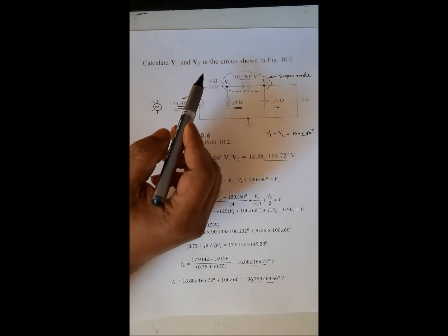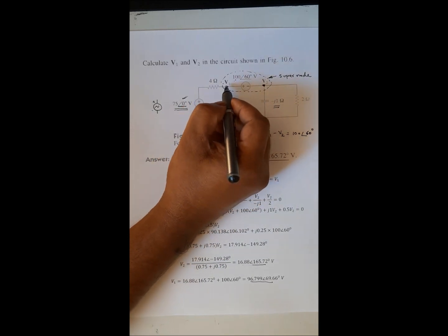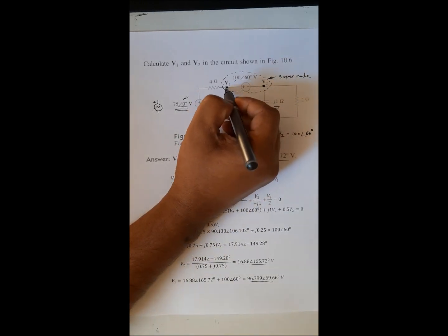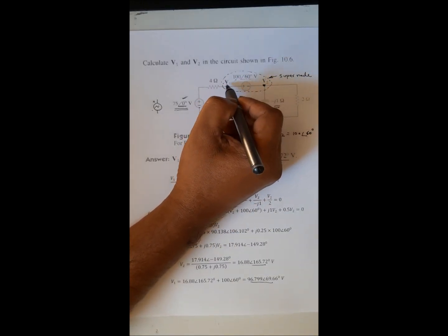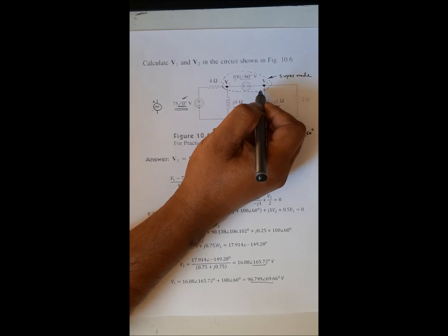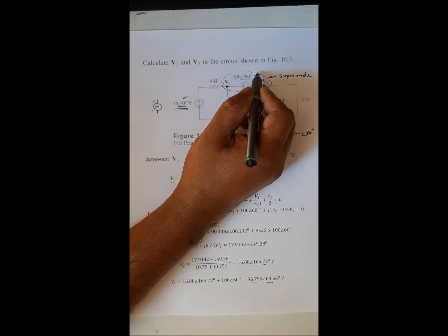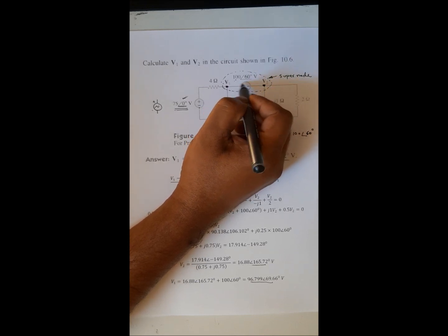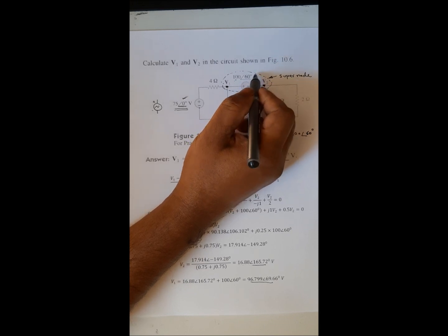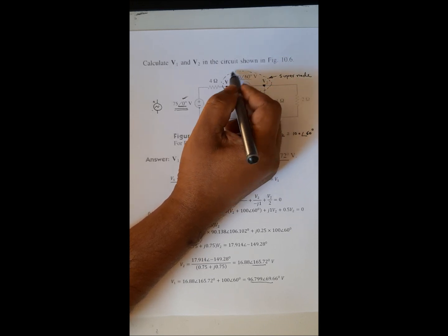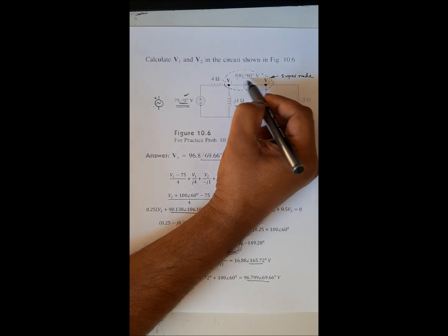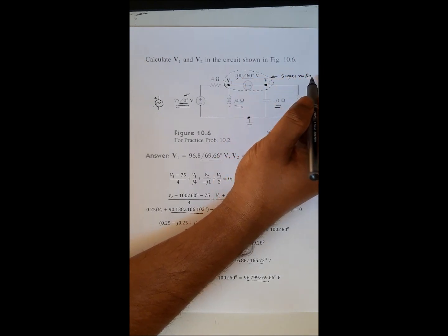Let me solve an example using nodal analysis. This is another example using nodal analysis. In this case, we have a node here, B, and another node here, and this is my reference node. You can see there is a voltage source between two non-reference nodes. As we know from our DC circuit analysis method, if you have a voltage source connected between two non-reference nodes, then we have to include these two nodes together to form a supernode. So here we have the supernode including V1 and V2. This is a supernode here.